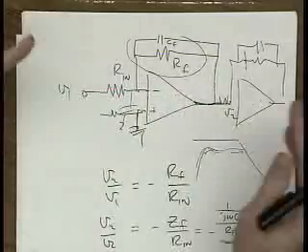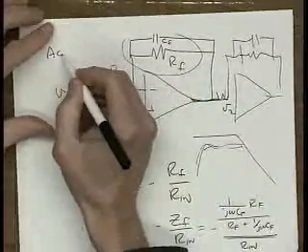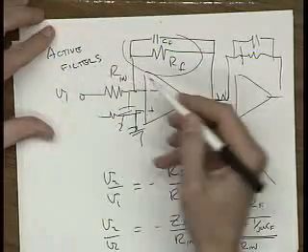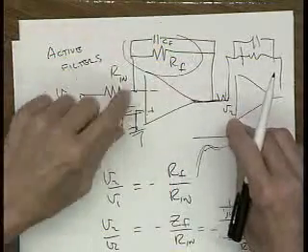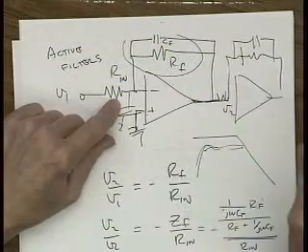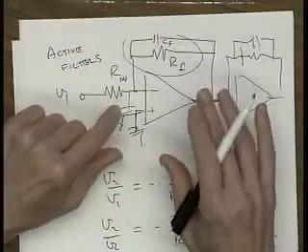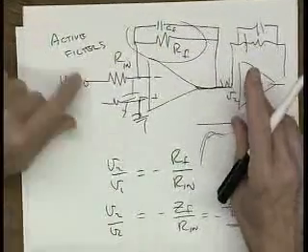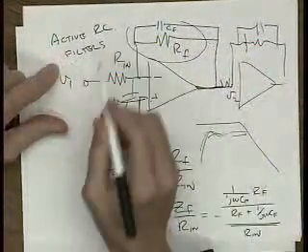And there's just a big literature. We call these active filters. This is the use of op amps and resistors and capacitors. Why don't we use inductors? Because this is generally at such low frequency. Baseband inductors will just be way too huge. So it's just usually R's and C's that we deal with. So these are active RC filters, what we call them.